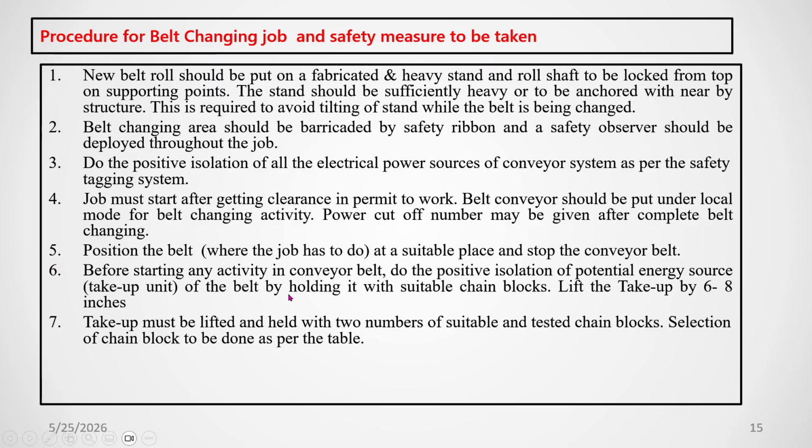You have to hold it. I have told you about the gravity pulley, otherwise when you cut the belt, due to the gravity weight it can fall down, and there will be a lot of accidents. So you have to first hold the gravity pulley and jam it there so that it should not move. Gravity weight should not move downwards, and then lift it by 6 to 8 inches above so that you can ensure that it should not fall down.